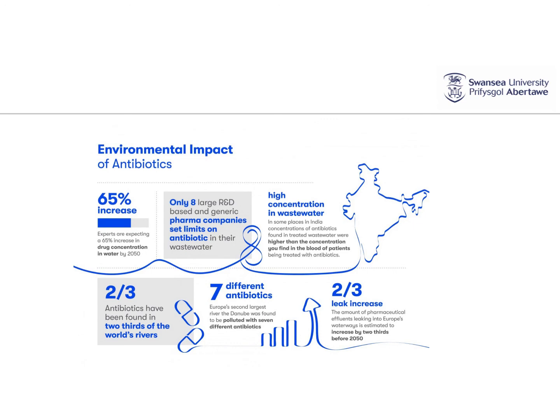Antibiotic pollutants may threaten the safety of drinking water. Drinking water sources may be contaminated by antibiotics. If the water purification plant cannot remove the antibiotics, they will enter the drinking water pipe network. As I mentioned on the previous page, sulfamethoxazole is the most common antibiotic found in rivers. And the study has shown that the influent water of 17 water purification plants containing the antibiotic has the highest concentration of 110 ng per liter. The influent of 11 water plants containing another commonly seen antibiotic has the highest concentration of 11 ng per liter.